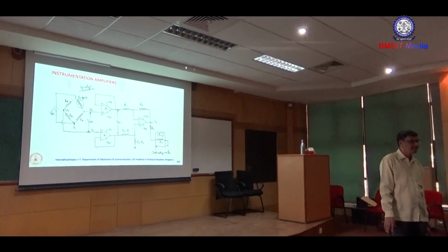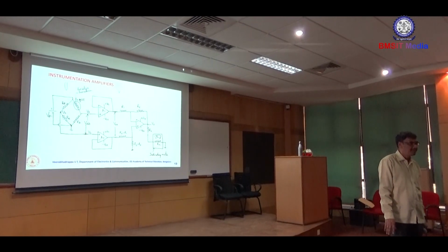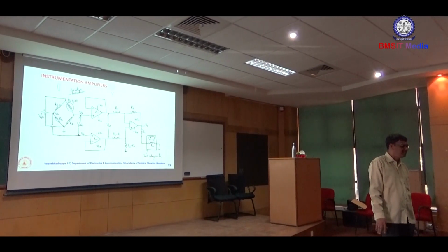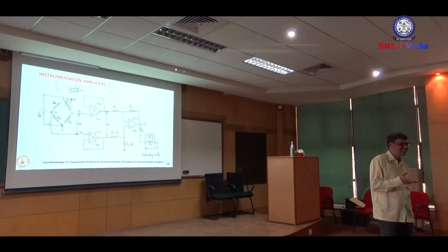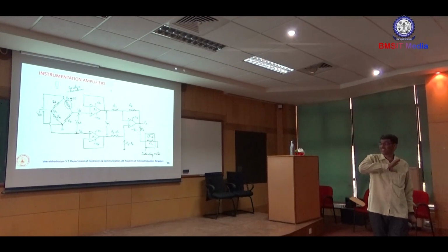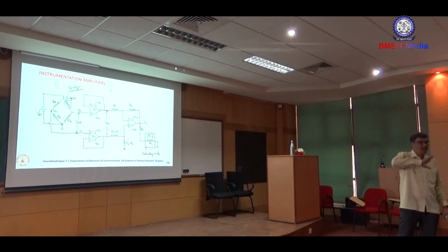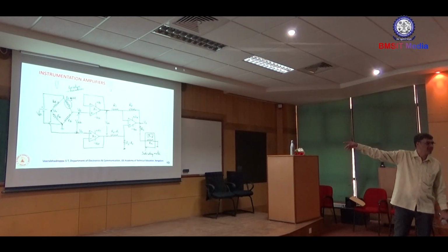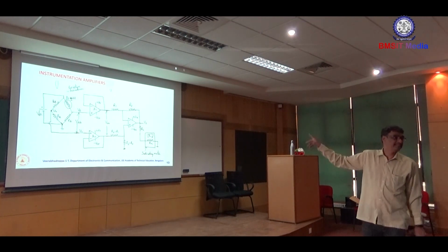Input resistance is increased by the beta. Common collector amplifiers, you don't have that in your syllabus, I think. I don't want to touch all those things. But that is an amplifier, because that unity gain voltage follower increases the gain also. Gain is to be 1 and input impedance is increased by the factor.